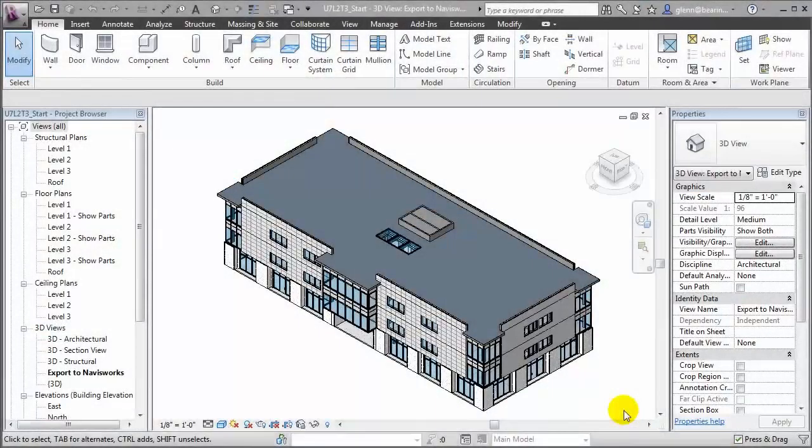We can also use 4D simulation to help plan and manage the ordering and tracking of materials for our construction activities. For materials management, we'll need to store and work with some new values for each of our building elements. For example, it would be nice to track the order date, the order status, the delivery status, and maybe even the location of the materials after they've been delivered to the site.